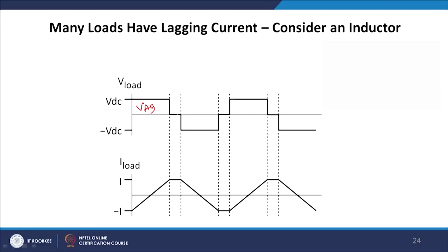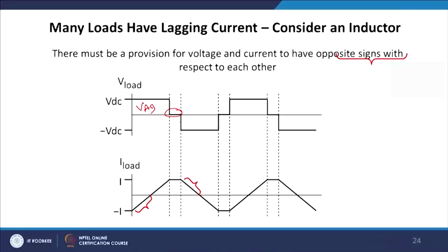Thereafter when you apply 0 voltage, current will be flattened, so current will flow through the diode in that region. Thereafter once you apply the negative voltage, then the current will drop and have a 0 cross. Thereafter the same will happen here in the plateau region. So by increasing this value you can increase or decrease the value of your RMS voltage. This is the operation of the simple square wave inverter.